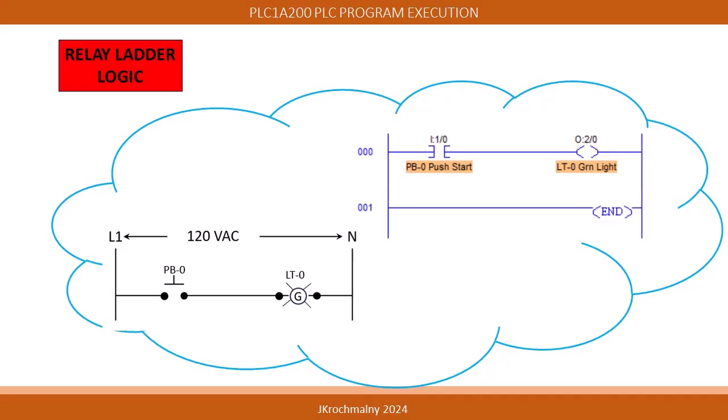The ladder diagram is used to create physical electrical circuits to achieve sequences of operation, and is also used as a foundation to write the program for PLC-controlled operation. In this graphic, we see the electrical diagram on the left. The diagram on the right represents the relay ladder logic programming language to be entered into the processor to achieve the sequence of operation.